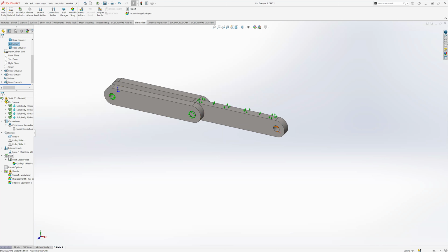So this should run a lot better now that everything is constrained. We'll go here, do a mesh and run, and this should run rather quickly. Usually if your study is taking a long time and it's a very simple study, that could mean there's an issue. Again, with the contact condition here, it may still take a little while, like 20 seconds or something. We're at about 15 right now, and we're running about 20 now.